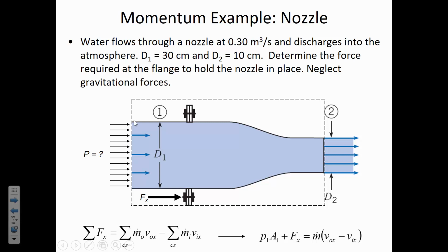Since we cut this pipe, and the pressure is on the left acting towards the right, that effect will be positive on the left-hand side. If the nozzle's direction was reversed and we were cutting some location where the pressure was acting from the right to the left, then this pressure term would be negative. We'll look at an example from the homework where that is the case.